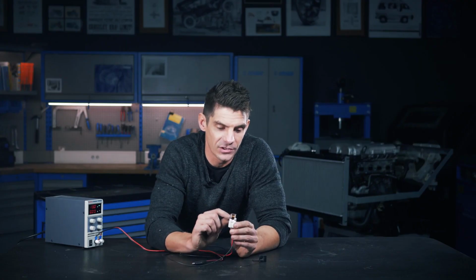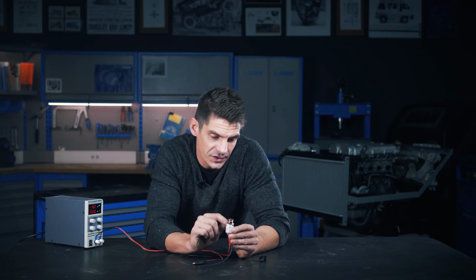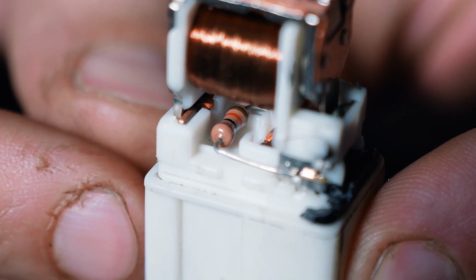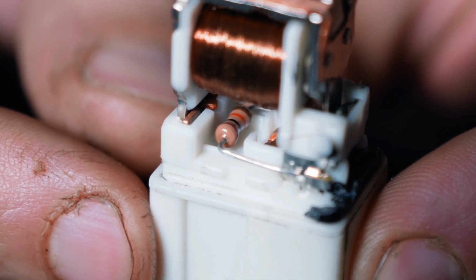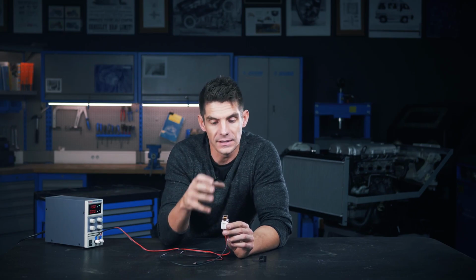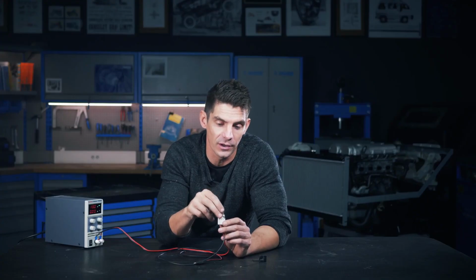There's an interesting detail on this relay. If you take a close look inside, you'll see that we've got a resistor connected across the coil in there. Now, what happens is when the ECU turns on the coil, it creates a magnetic field. When the ECU turns off that current, the magnetic field around the coil collapses instantaneously, and that collapse is a huge change in the field, and it actually induces a voltage into the coil itself. That voltage can be hundreds of volts, even though there's almost no current, but the voltage alone can be enough to damage the ECU or any electronics that are connected to the coil. It kind of travels in reverse, known as a voltage spike.